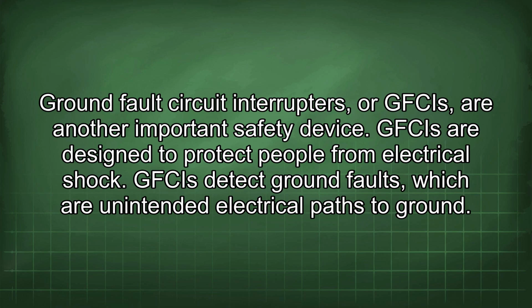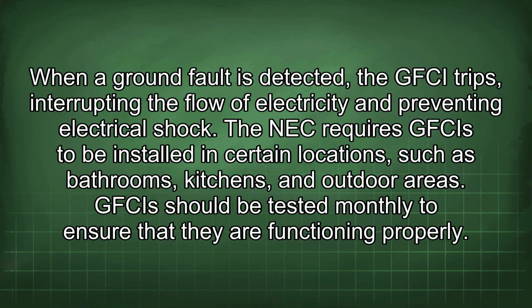Ground fault circuit interrupters, or GFCIs, are another important safety device. GFCIs are designed to protect people from electrical shock. GFCIs detect ground faults, which are unintended electrical paths to ground. When a ground fault is detected, the GFCI trips, interrupting the flow of electricity and preventing electrical shock. The NEC requires GFCIs to be installed in certain locations, such as bathrooms, kitchens, and outdoor areas. GFCIs should be tested monthly to ensure that they are functioning properly.